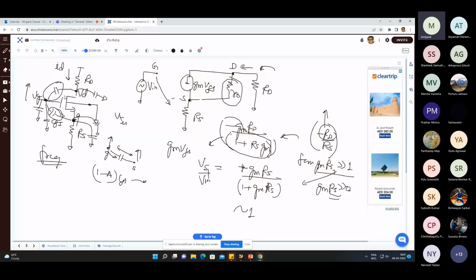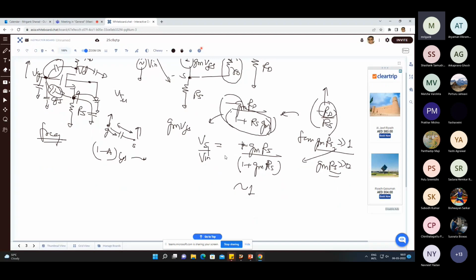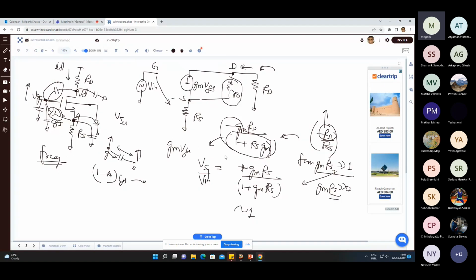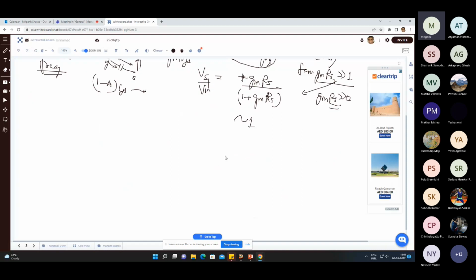This one is having Miller effect. For the Miller effect, the gain that you will use is a modified gain over here, and then you can figure out the node capacitances at all these nodes. Only thing is, even after breaking these capacitances down, your analysis is still a little bit complicated because of the capacitance coming here. So suppose you apply the Miller effect, you get CG equivalent, because that is the equivalent capacitance between the gate and the AC ground.